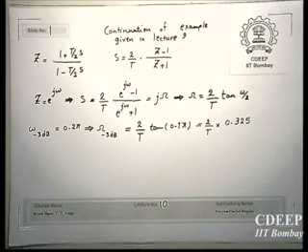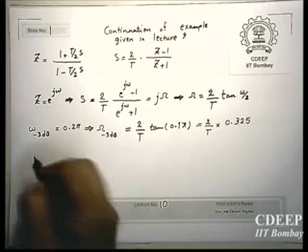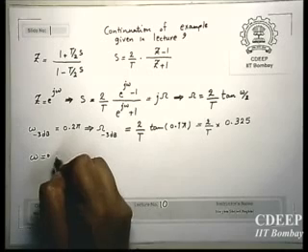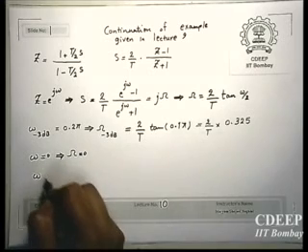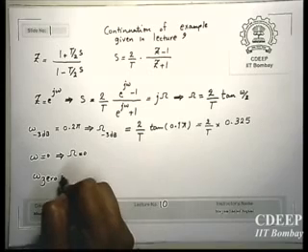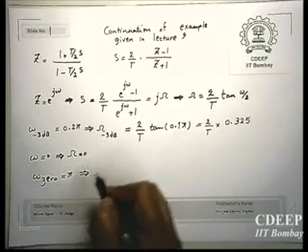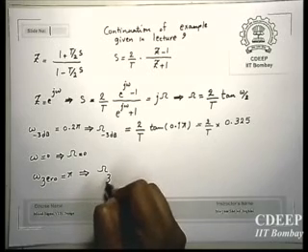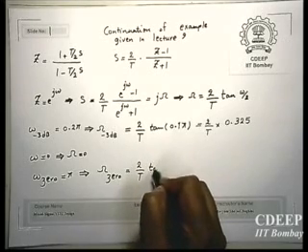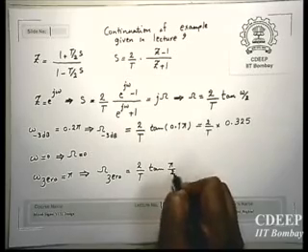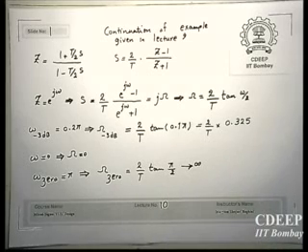Okay, so now just this 2 by T appears everywhere. Then if small omega is equal to 0, capital omega will be 0, and then we have a 0 at pi. So what will be the corresponding frequency in continuous time? That of course will be 2 by T tan pi by 2. Therefore this will be infinite. So this means that if you have a 0 at pi, it makes sense, right?